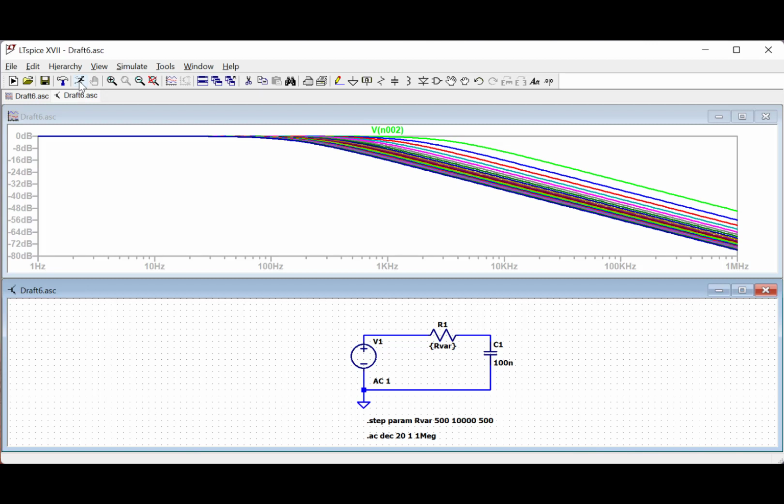This is a very powerful tool that you can use whenever you need to understand what's going to be the behavior of your circuit under different values of a given parameter. My strong recommendation is to use this in order to verify some hypotheses and not to design a circuit. Don't be the kind of student who just tries random numbers in order to set up a cutoff frequency instead of calculating that. Start always from a manual calculation and then find your way to verify your hypothesis by means of, for instance, parametric simulation, as we have seen in this tutorial.